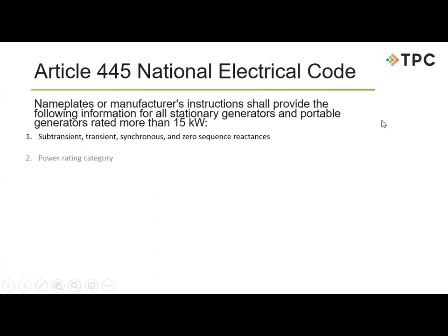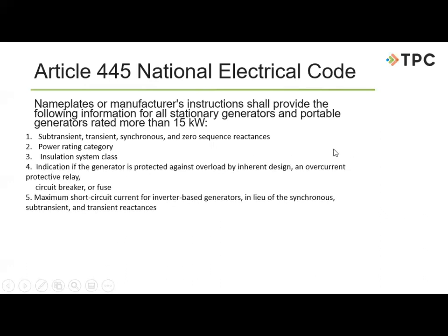And take a look at now of course, the power rating. So we are going to know how many megawatts it is, or kilowatts, or whatever the generator is. And then the insulation. So they're always going to give us a couple different choices here. It is either going to be an insulation of H or F. And I can tell you that H is the higher of the two ratings. So if you have a generator that is continuous duty, it would definitely be an H insulation, but we'll see some of these on the nameplates that we're going to see.